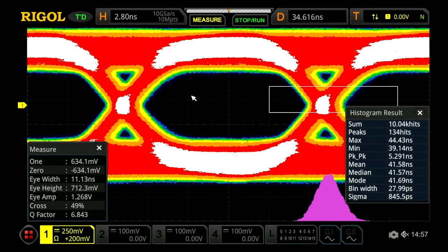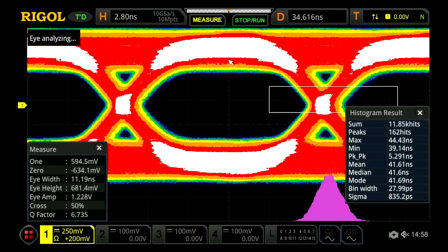We can actually see in this eye diagram there are a couple different issues impacting our results. One, we see vertically a lot of space here. This implies a certain amount of noise coming through the signal that might be affecting our ability to get a clear bit test at this point.